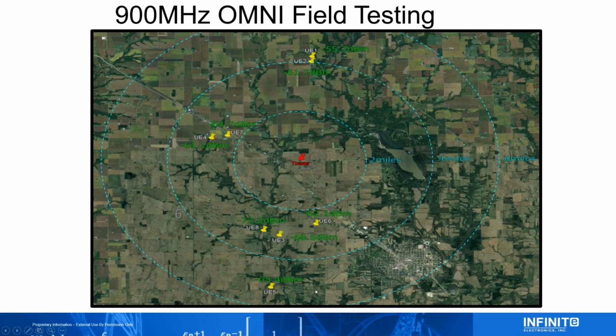So they're getting very good signal strength out very far. He wasn't trying to pick up lots of clients with it, but just a handful, a typical Omni application, serving your CAF funding required download and uploads. And so, yeah, he was very happy with this antenna. He bought multiple ones and put them in many different locations because it's a very cost-effective solution. You don't have to buy multiple APs at 900. A lot of people still love 900, even though it's noisy, but certain areas have different noise characteristics. So it really is just choosing the right frequency for your application.